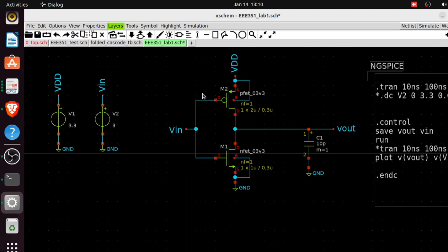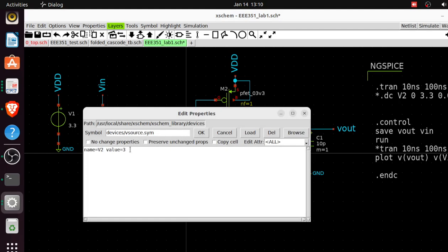So for digital simulation like this, I want to use a square wave, right? Something that rises, then gets flat, maybe that will be a 0, then comes down again to be a 1. To do that, that's my V in, which I'll make a pulse kind of square wave voltage form. So I'll double click and remove that 3.